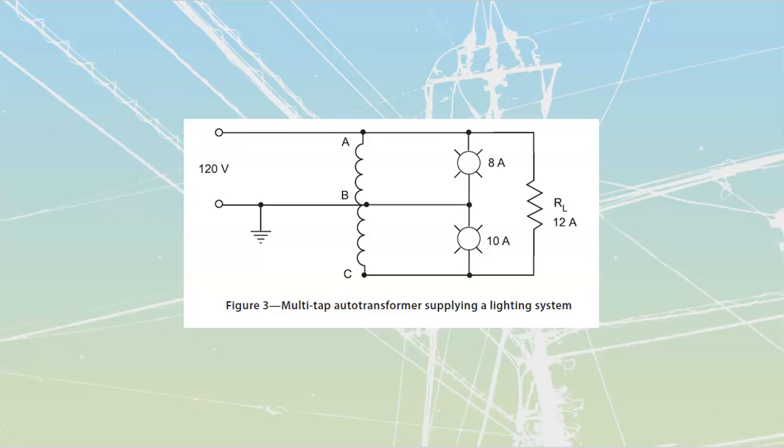It says that this thing is a 120-240 autotransformer. This would make sense, right? We know that this is going to be my neutral. We know that this is going to be my line. We know it's the neutral. It's the one that's connected, first of all, to the center point where a neutral has to be, but also they show us that this thing has been identified as also being grounded, back at the source, not at this transformer, but back at the actual source itself.